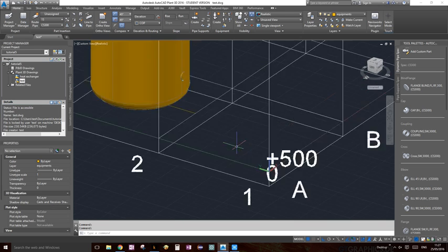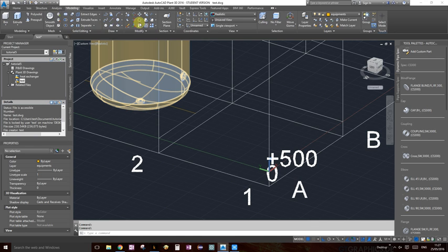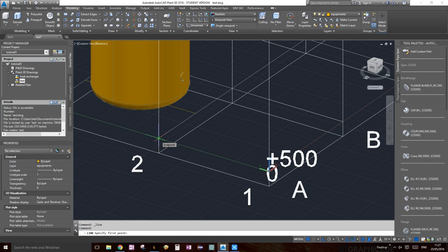The second thing we're going to do is add a pump. Again, you would have dimensions of how far it needs to be from a certain grid point. So let's go ahead and draw a line that would define how far away it needs to be. Let's say we wanted 500 millimeter this way. So let's type 500, enter. Okay, maybe 500 is too little.